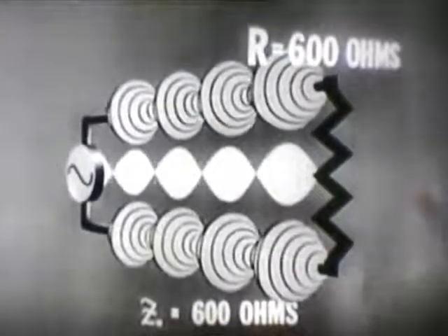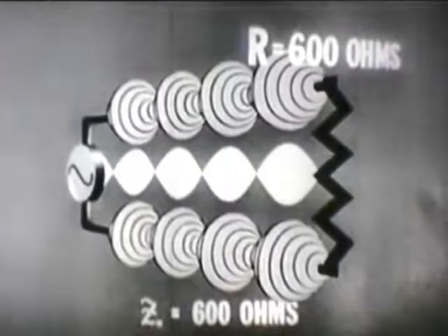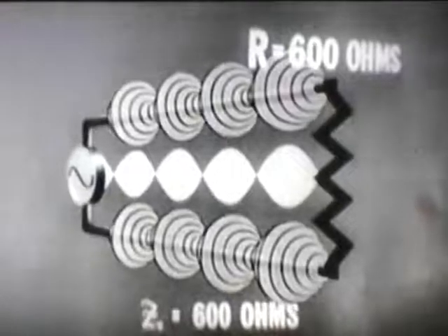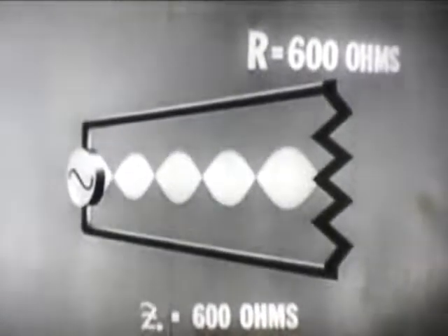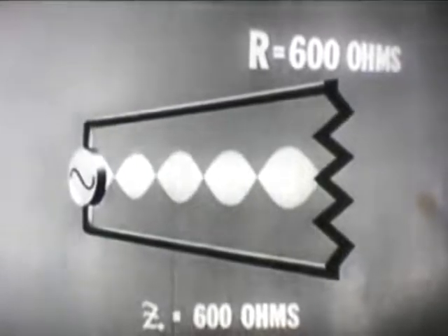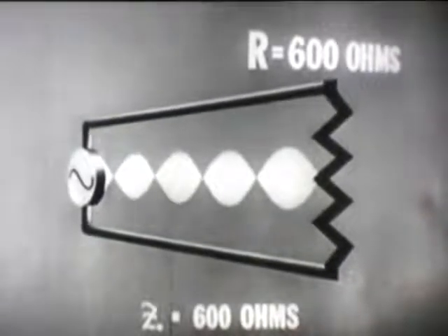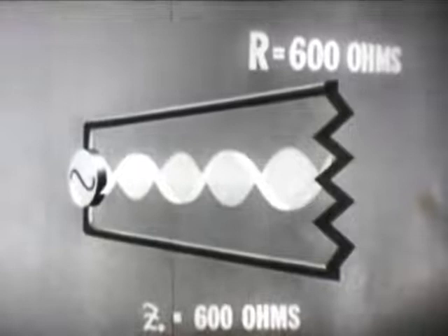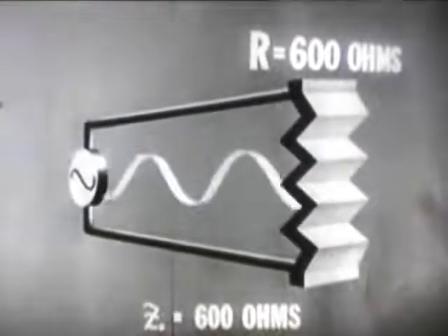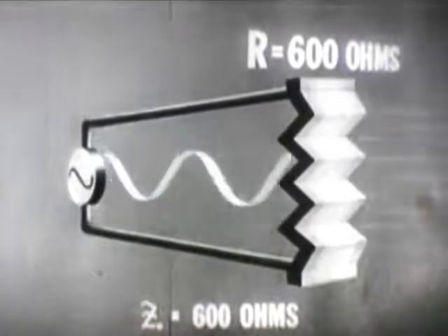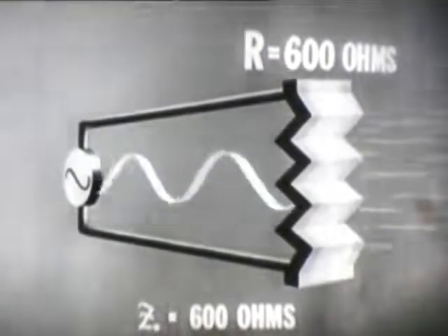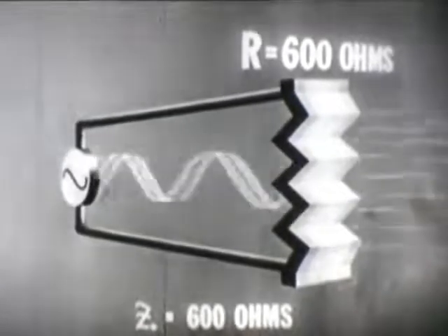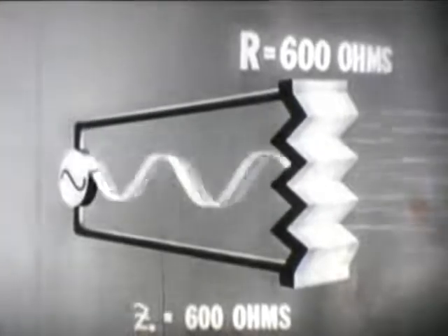Our alternating current patterns still look the same, although the infinite line has been changed into a practical line. For a simpler demonstration, let's use a single part of the pattern, in this case the voltage field. And since it is easier yet to use the sine wave of the voltage, we can represent the voltage field by a voltage sine wave. Here the sine wave indicates the alternating current in the line. The energy that hitherto charged the infinite line is now being dissipated by the resistor in the form of heat. To put it another way, the energy of the electric field has changed to heat energy.